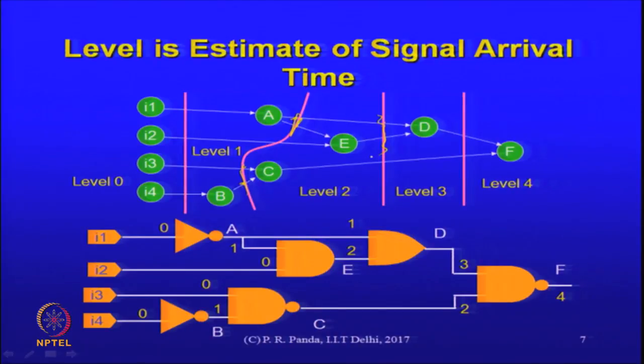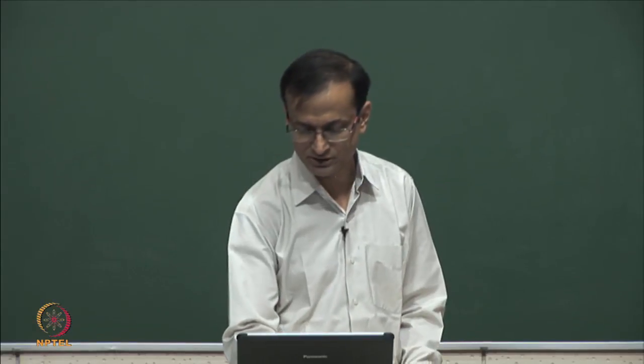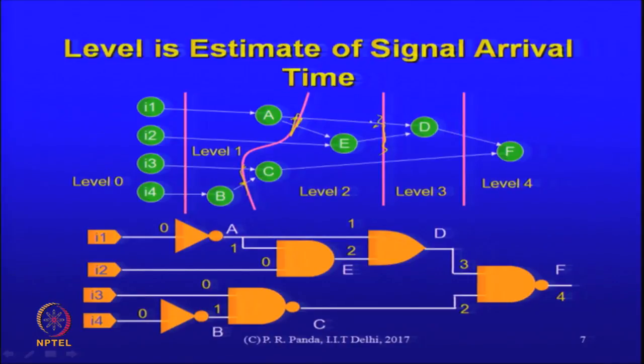So here the assumption is that all the paths have the same delay, right? No. Otherwise the paths are different. Oh, we are saying that at that time all the inputs are ready. So, for D you can see that one of its inputs got ready earlier. Okay. It is this one that arrived later. The computation of D essentially starts after all its inputs are there. So, timing analysis of this circuit means that you are finding what is the maximum level of this circuit.